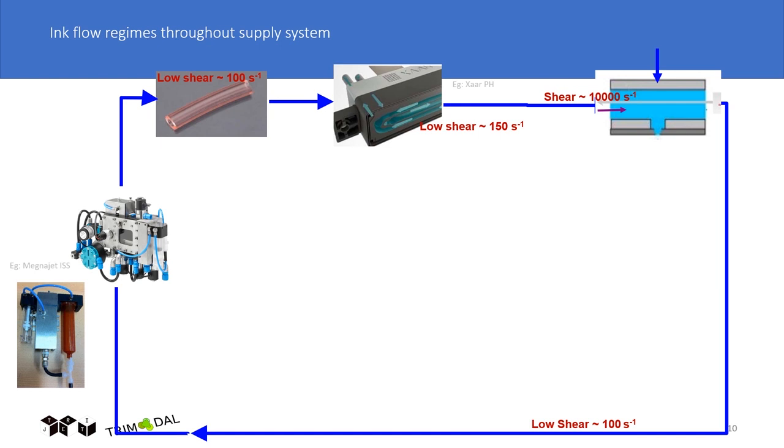It goes about 10,000 shear rate, okay? And then what you do, you activate the piezo when you're driving it. So your waveform would be about hundreds of kilohertz for each sub-drop. So you're talking about hundreds of kilohertz, and the total printing would be 6, 7 kilohertz to 30 kilohertz, depending on what mode you're printing.